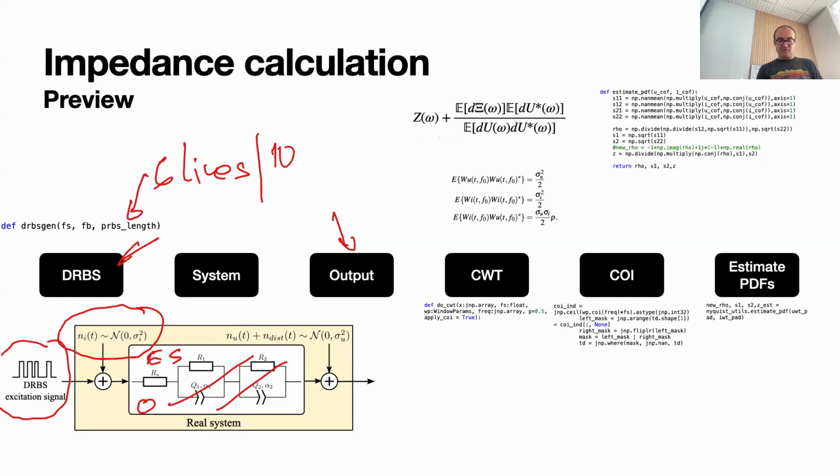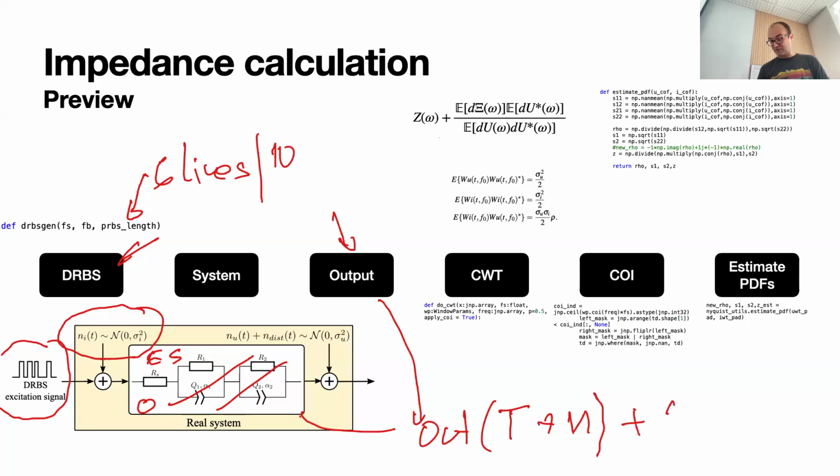So our fuel cell system is actually getting our ideal signal plus some noise, and what comes out is the system output of our true signal plus the noise. On top of that, when we try to measure this output, Mother Nature provides an additional noise, called measurement noise. And these are the signals that we are dealing with.